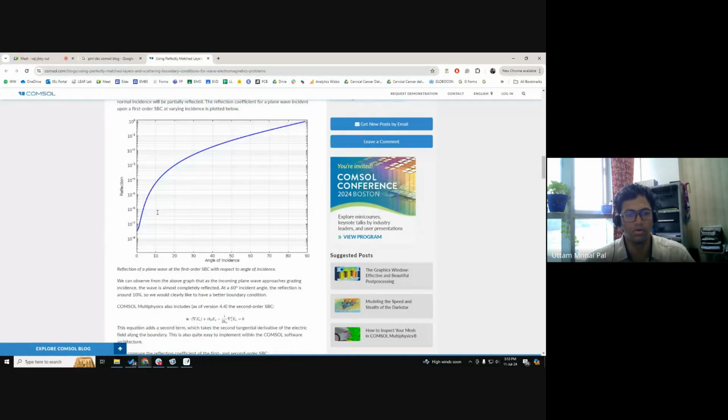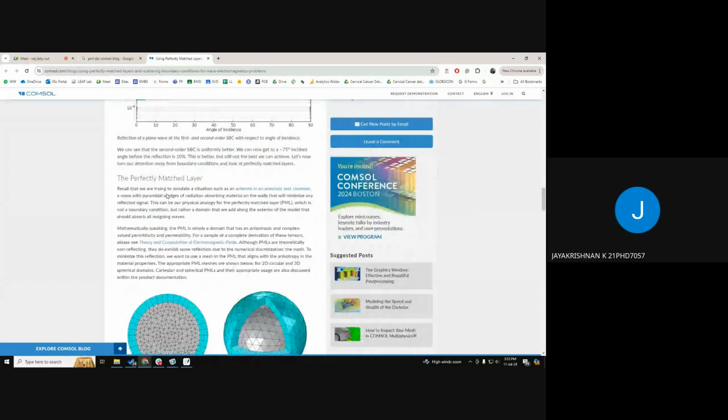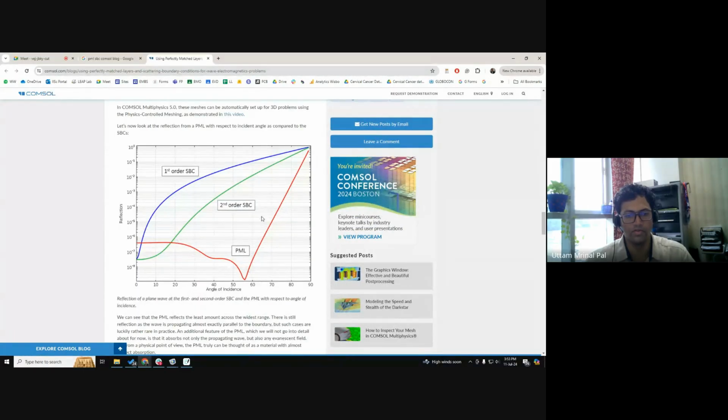PMLs are the best way to reduce this reflection, even for higher angles of incidence. The only challenge with PML is that the computation time significantly increases. Other than that, there is no problem with PML. So ideally, it's good to use PMLs instead of SBC any day.